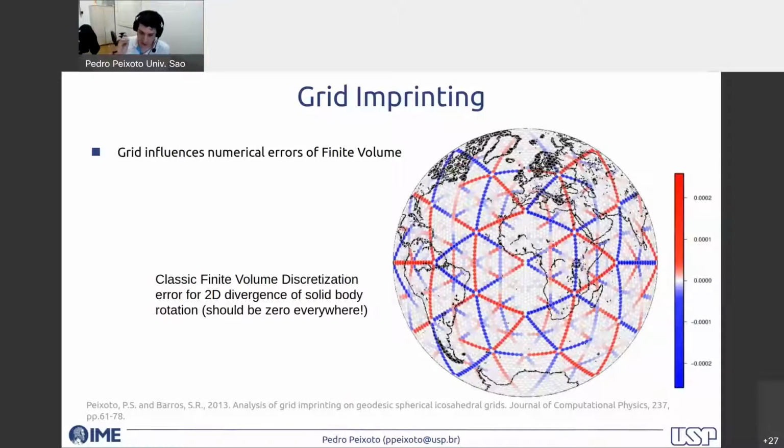And now it comes to the part of the talk where I discuss some issues that will arise in MPAS. If you note these in your simulations, you should be aware of these issues so that you know where they're coming from. One of the interesting things is that dealing with these grids is non-trivial. So if you take a solid body rotation field, which means the velocity is simply a rotating field, and you just calculate the divergence as the method used in MPAS does, what happens is that in the error which you see in your field, you can basically see your grid.